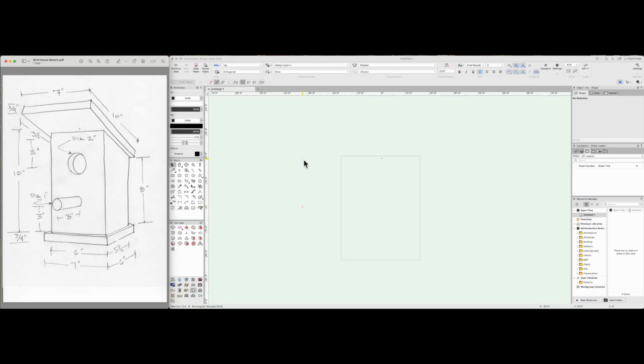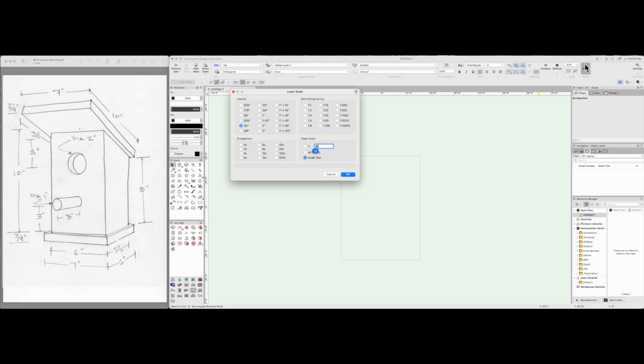All right, this project is the Birdhouse project, and as you can see, I have the Birdhouse on my screen, just like you will have a printed out version. I've opened up the default when you start Vectorworks, which will be an untitled document. You can see it's right here. The first thing I would suggest doing in the titled document is go up and change the scale to 1:1, because the birdhouse that we're drawing is small enough that you'd probably draw it in 1:1 scale.